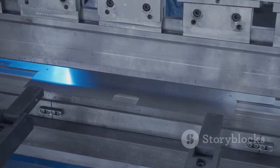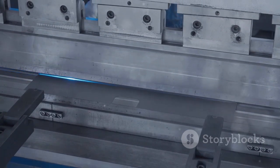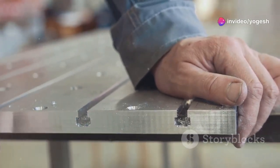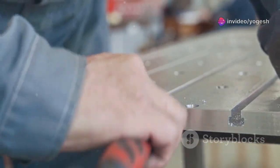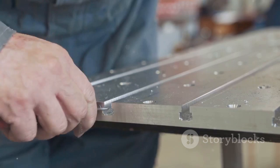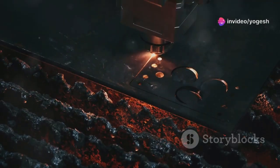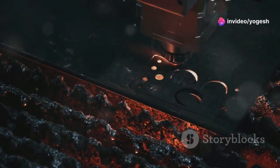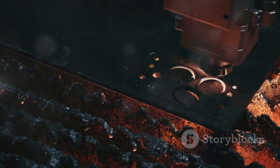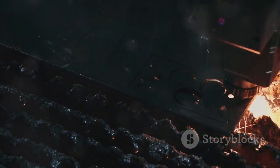Use the base flange tool to set the uniform thickness across the entire part, ensuring structural consistency and manufacturability. Next, add 4 50 mm high walls using the edge flange tool. Set the inside bend radius to 1.5 mm, which matches the material thickness and helps prevent cracking or deformation during bending. Adjust the K factor to 0.44 for accurate flat pattern development. This value compensates for material stretching and ensures your flat pattern will fold into the correct shape.